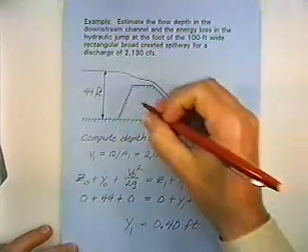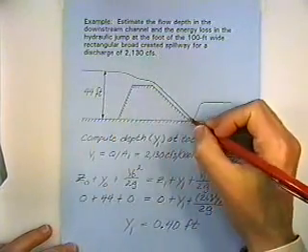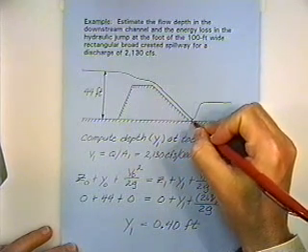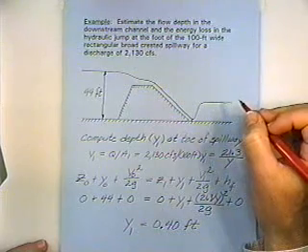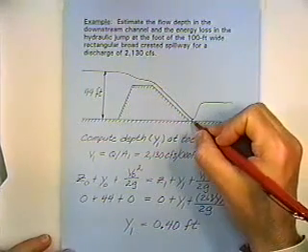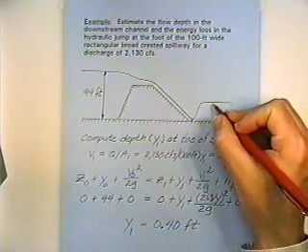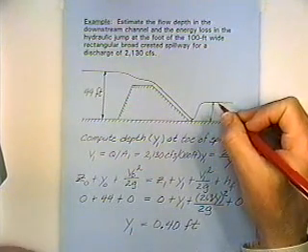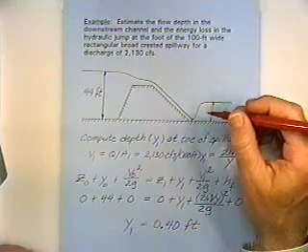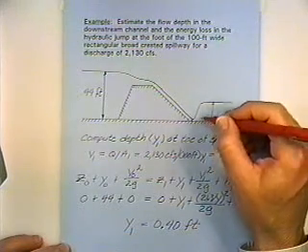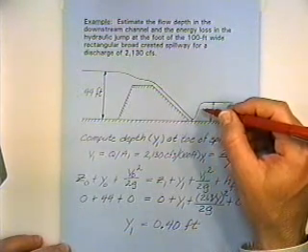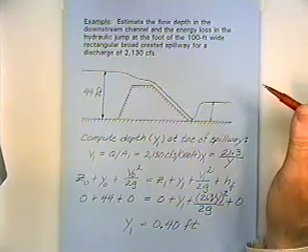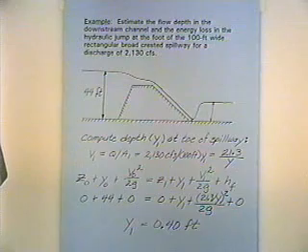The first thing we want to do is, knowing the depth upstream of the dam, compute the depth at the toe of the spillway, and we'll use the energy equation to do that. Then, knowing the depth at the toe of the spillway, we'll compute the depth downstream using the conservation of momentum equation, because we're forced to do that: the hydraulic jump is dissipating so much energy that we cannot compute that head loss any other way.